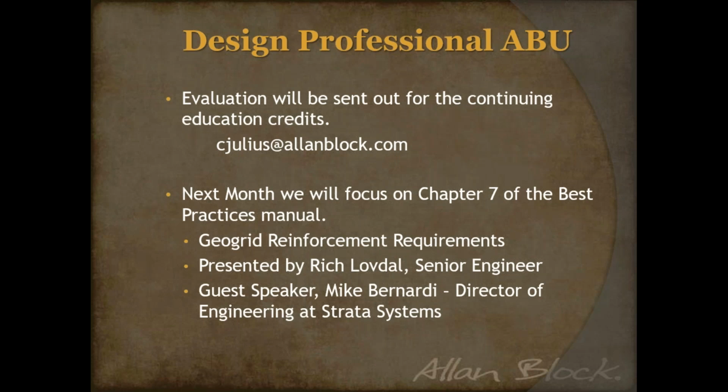We did have another question pop up. It says, how do you know what the optimum moisture content is, and how do you get the soil to that content in situ? Yeah, the optimum moisture is usually a couple different ways. We're doing a couple different tests, plasticity index and stuff like that. But when you're talking compaction, it is all that Proctor test. And so that Proctor test will give you the optimum moisture.